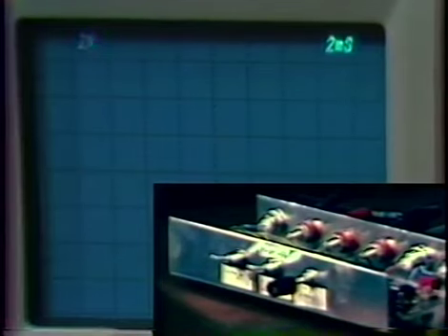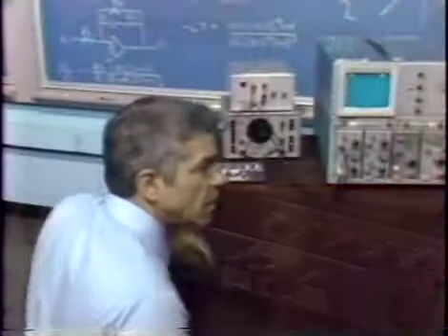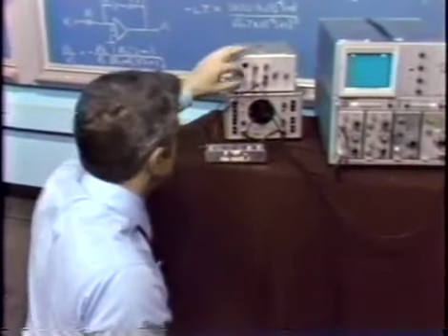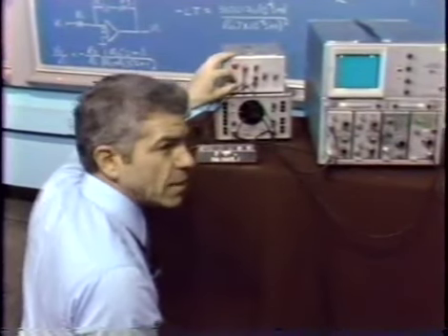Let's see what happens if we turn on the power supply. Whoops, we lost. This is really a flip the coin kind of situation, because it's entirely possible that during the startup transient, we somehow kick the system, get into the large amplitude case, and the system oscillates. That time we won. I turned on the power supply, turned it off, turned it on again. Turns out this time, just by flipping the coin a second time, the system started in the stable mode. We now have the large value for A0, an A0 of about 80.